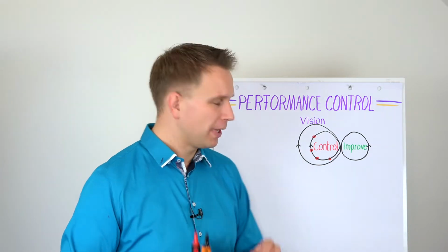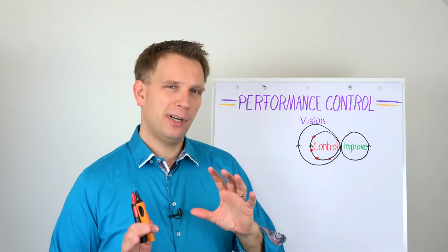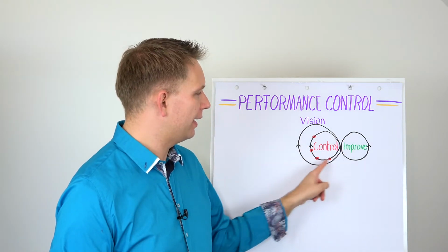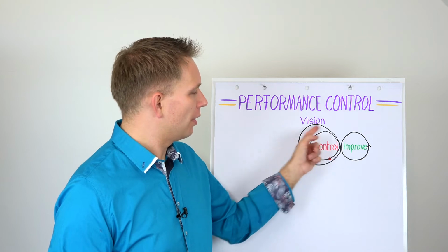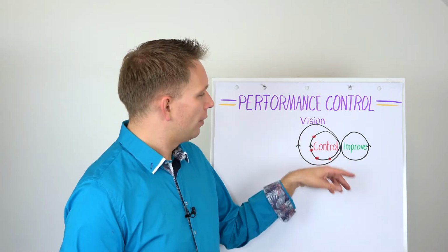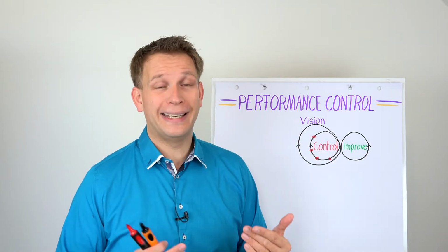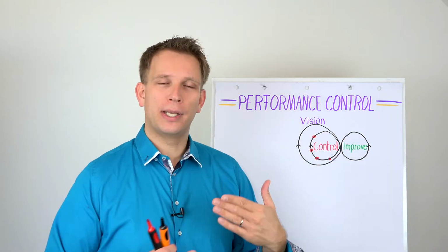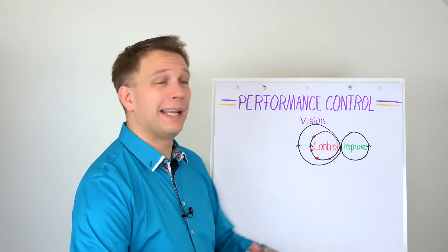What you then basically do is you go into this infinite loop and you say, the cleaning time part, we have a nice standard, we just have to keep it up. So we're going to control it, and this circle will run a lot faster than the big circle. This is basically daily control. So every day we're going to check that the cleaning time is still what we planned it to be and not deteriorating. For the breakdowns, we have to do two things. So first off, we're going to daily control that we are at least not slipping away from our current level, but we're also going to plan an improvement project where we are going to tackle a specific part of our breakdowns, make sure that we have fewer breakdowns and increase our performance.